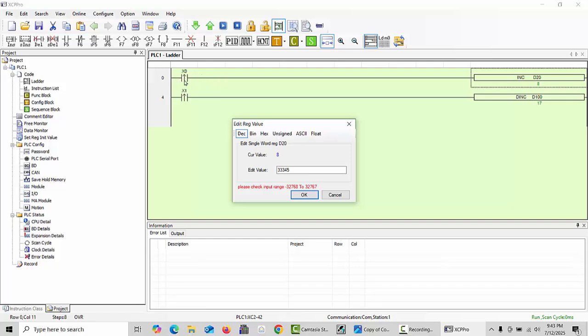But when you are using it in a program, you can physically check with your counter. In the hardware there have to be some sensors or actuators connected with your X0 and X1, that will be giving the signals. The INC command only supports values up to 32,767. But for example, if you want to store a big value, above 32,768, so what to do? This way we cannot use INC.